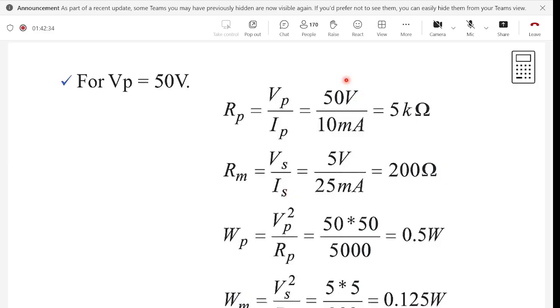So from the software, we can convert this 5 volts to 50 volts by multiplying 10 times. So let's say the actual voltage on the circuit is 25 volts. So the microcontroller will read 2.5. Okay. Then we will multiply it in the software by 10, get 50 volts. So that the microcontroller will know that it's 50 volts.